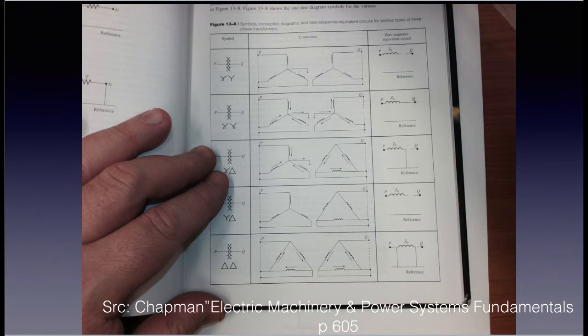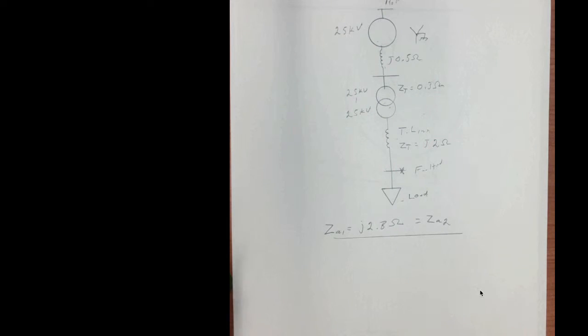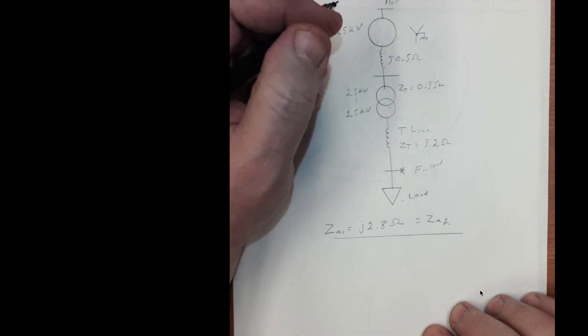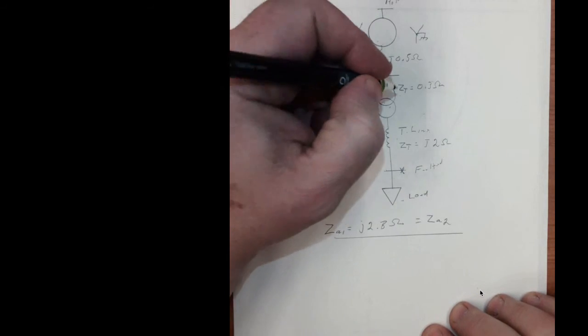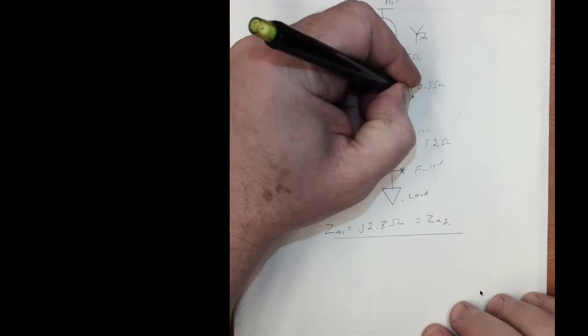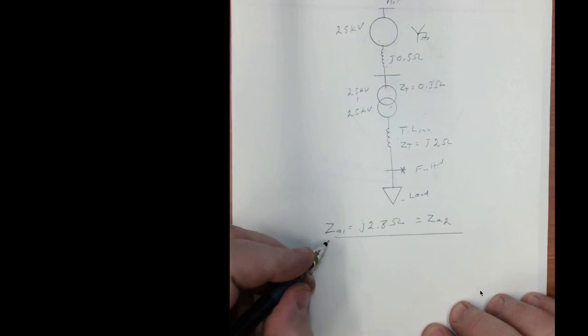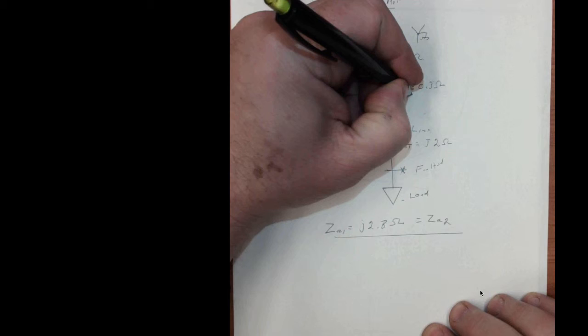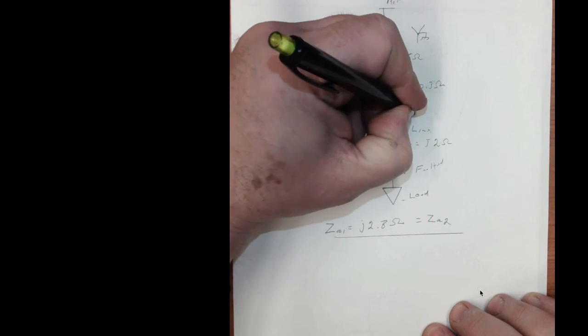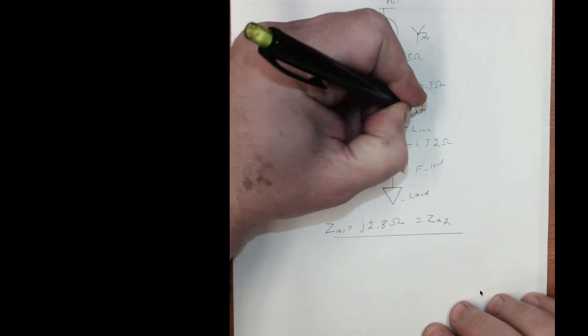So let's go back and look at our schematic or single line diagram and put some values on here, how we would come up with our various impedances. The one that's of interest to me, I've already found the positive and negative sequence. Now on this transformer, I'm going to make it Y delta with a ground here.